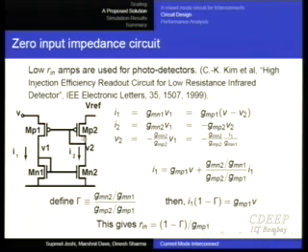Right? So therefore the current fluctuation through this, which is I2, will be GMN2 V2, because V2 is the fluctuation here, and this is the GM of this transistor, and that is equal to GMP2 times V2.